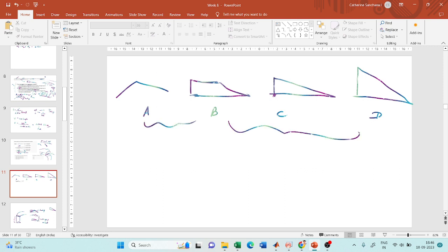This entire stretch is the super elevation runout, as I said for the question. But when I explained, I told you that this has to just move up and it will become a triangle like this, which looks like a super elevated section. But still, I did not say that is the super elevation runoff. I told you that BD is the super elevation runoff.